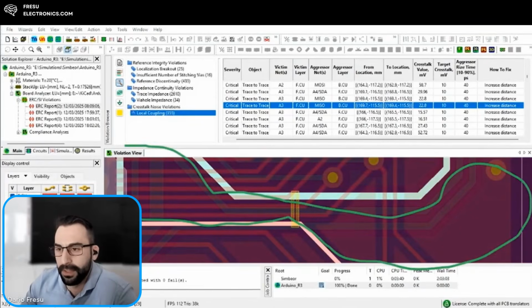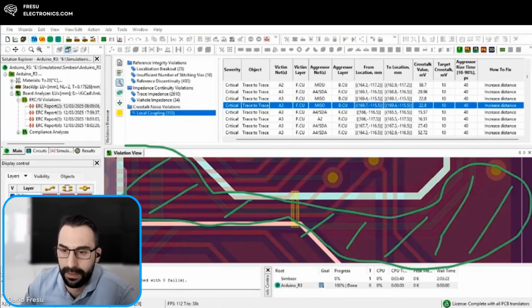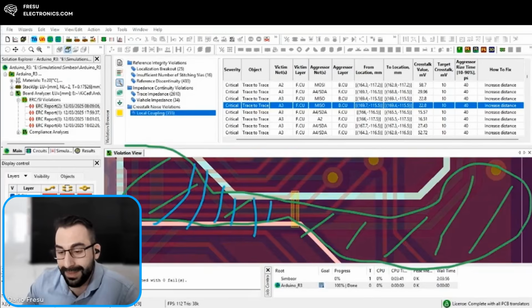If I know that the radiated emissions from differential mode current are related to the area enclosed by the loop, look at the area that this loop is enclosing. Then I can put this in the formula and calculate it. So just by looking at this current loop, you can calculate what the emissions from differential mode current are going to be from your board. Now, the other problem this is going to create is that when the reference is trying to be established between the signal layer and the return reference, I'm going to have a certain impedance as well.